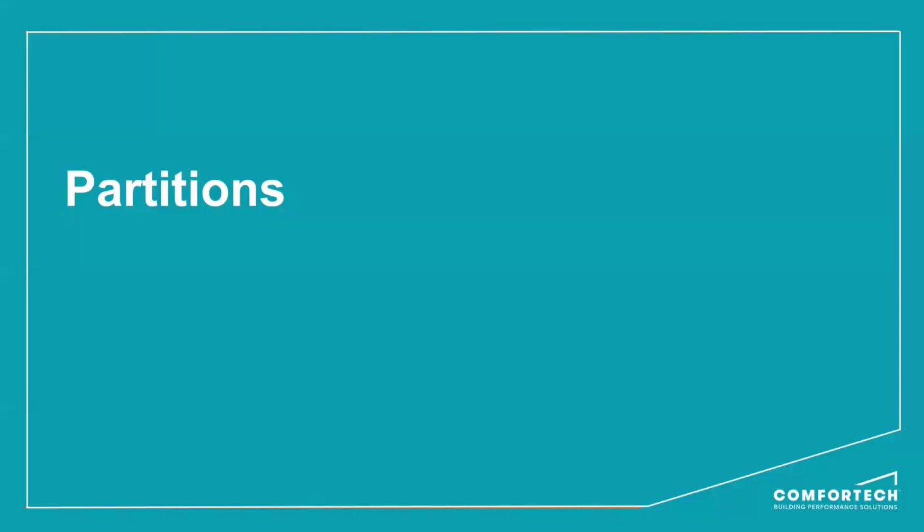So on to partitions now. Again, we need to ask ourselves, what's the purpose of the partition? Is it for acoustics? Does it need to be fire rated? Is it going to be taking that ceiling seismic loading? Is a shelf going to be hung off it? What are the services in the wall? And again, by thinking about what the intended purpose of that partition is, we can refine that selection down to offer the best solution for your design needs.